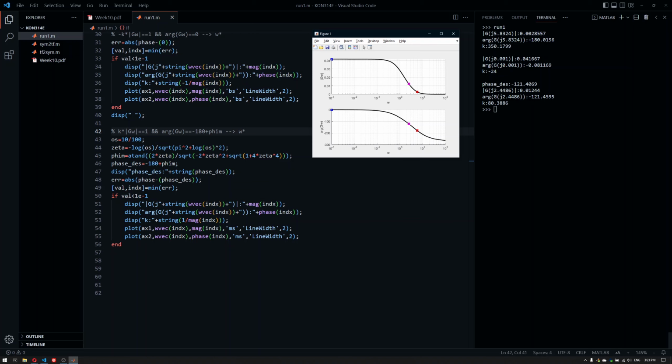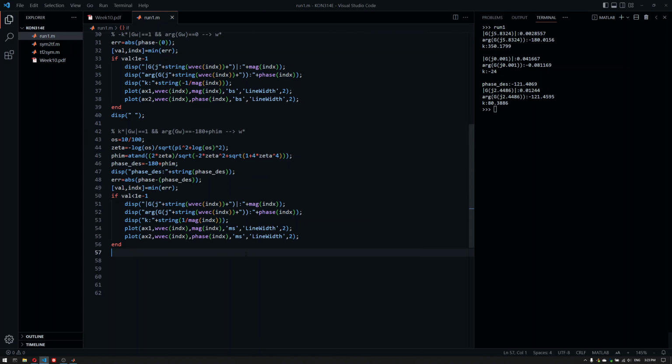So we've practically designed a P-type controller by just looking at the Bode graph and calculating the relation between overshoot, zeta, and phase margin. Using the phase margin, we just skipped a little bit to the left, took the magnitude here, inverted it, and that's basically it. So let's see what happens if we really do this.